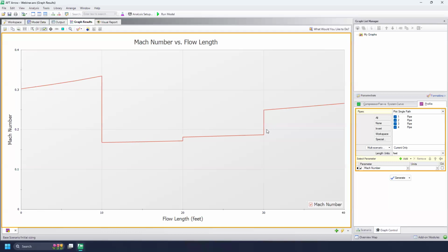If you have something there where you could model it more specifically, let's say part of your machine is on a skid and you have a lot of bends and piping that you could model, try to capture as much as you can. Because of the way this acceleration is working, you can end up getting different results if you group everything into a single loss at a point versus having it distributed.